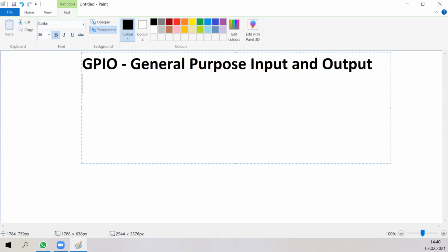So another thing that the microcontroller can do, we will want to teach the microcontroller to speak to us, to send us some messages. And to do that, we usually use a peripheral called UART, Universal Asynchronous Receive and Transmit Peripheral, which can send text from microcontroller to, for example, CPU.